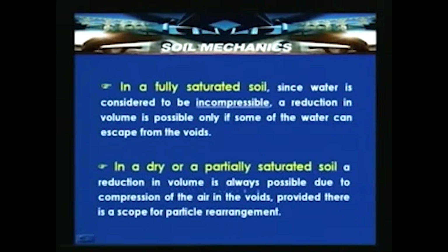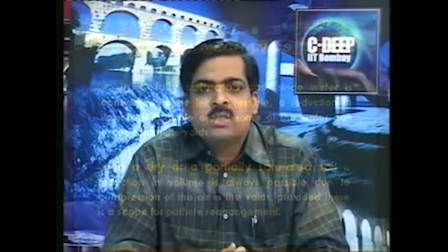In a dry or a partially saturated soil, a reduction in volume is always possible due to the compression of the air in the voids, provided there is a scope for particle rearrangement. That means that whether it is in a dense state or in a loose state, particle rearrangement will take place accordingly.